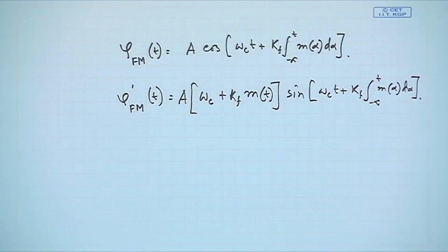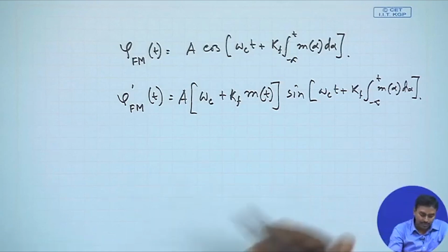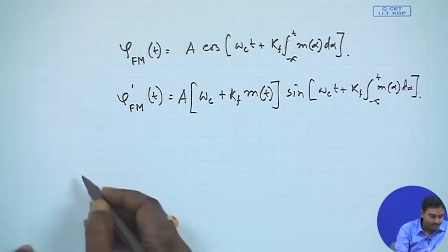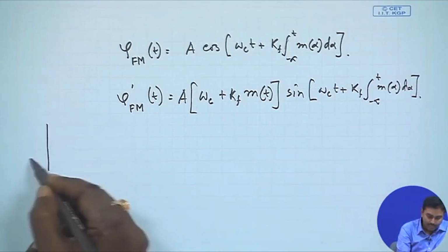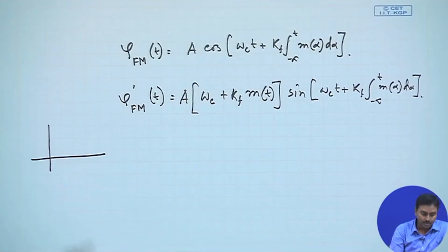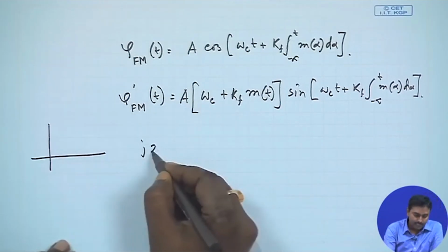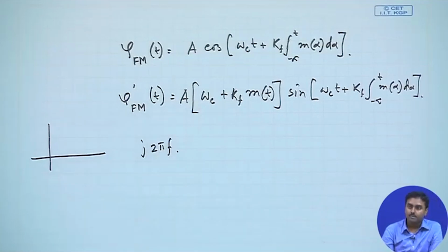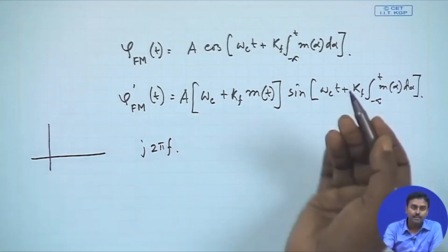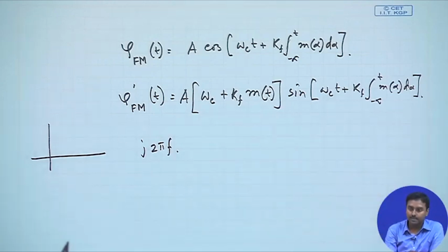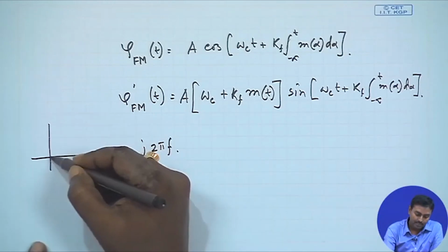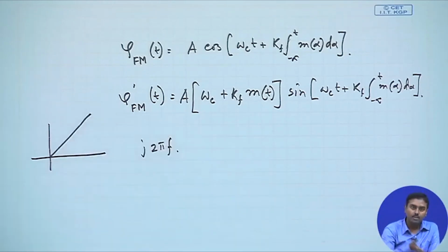Okay. Now, whatever the sinusoidal, it will actually look like this. Suppose an ideal differentiator, how does that look? That is generally j 2 pi f, d/dt, if you take the corresponding Fourier transform. So, that looks like this. So, the ideal differentiator's amplitude part should look like this, it is a linear function of f.